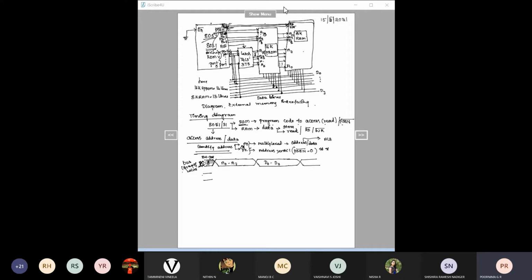So now another port whose contents need to be taken care of by the 8051 is port 2. Port 2 will be having the address, that is A8 to A15, with respect to time only. Here you have to consider this is with respect to the clock pulses, like this it will be varying. Okay, now A0 to A15 will be available for this complete duration.